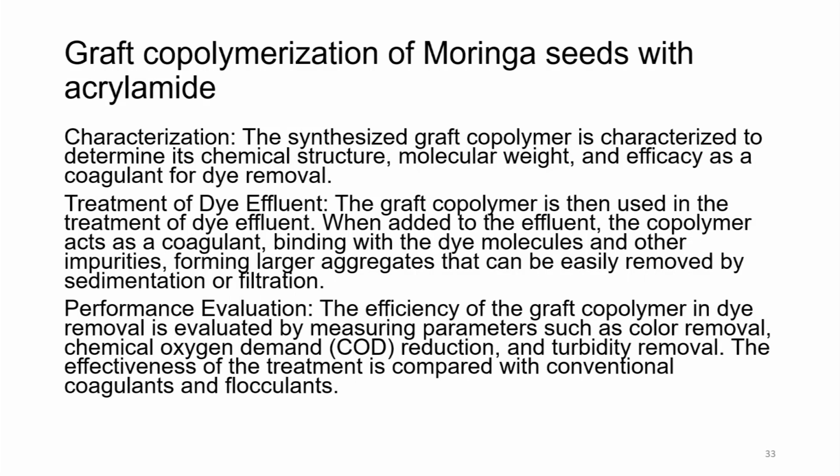Performance evaluation. The efficiency of the graft copolymer in dye removal is evaluated by measuring parameters such as color removal, chemical oxygen demand, that is COD reduction, and turbidity removal. The effectiveness of the treatment is compared with conventional coagulants and flocculants.